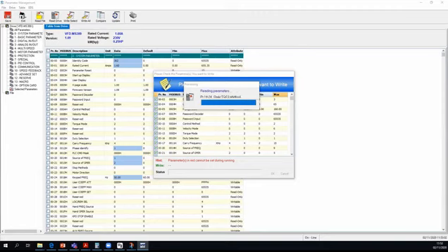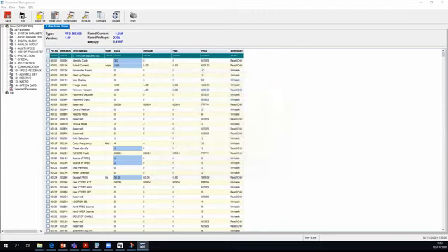Oh, in the meantime, I see there is another question. So in point-to-point mode, can you use parameter 415 and 416 to set a command from the drive only? Yes, that is possible. You can have a range of different combinations for the digital inputs, and then you can just send the drive to a position based on those parameters. In fact, we have a quick guide on that.